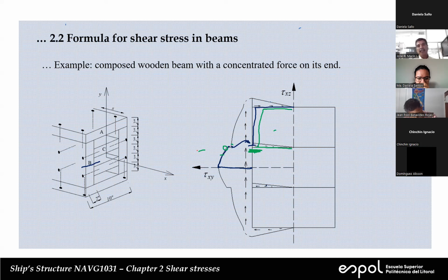And that's what we see, that we have linear variation of shear stress here and also linear variation of stress here. If we go on in the upper direction, we can see that we have a web, and every time we see a vertical element, the variation is quadratic. That's what you're seeing here. This is a quadratic variation.